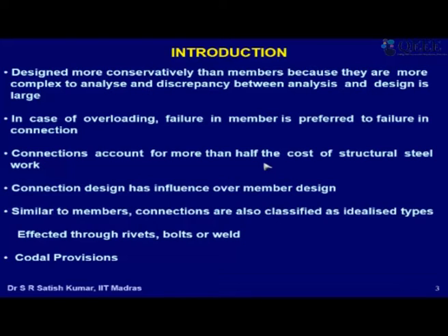In the beginning itself, if I assume 3 bolts, then I may be doing an uneconomical design. I'll have to provide a larger member cross section to cater for that. So that is also not desirable. Those are the issues in design.